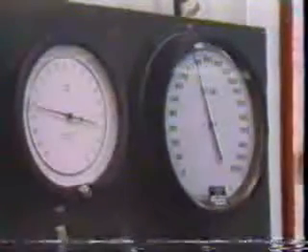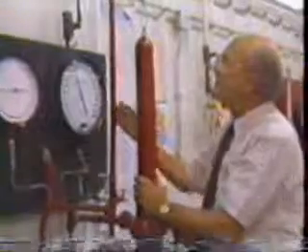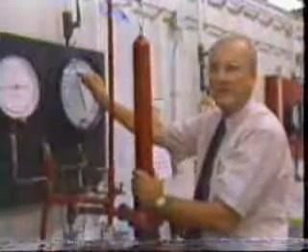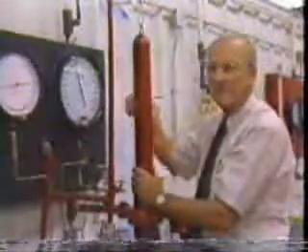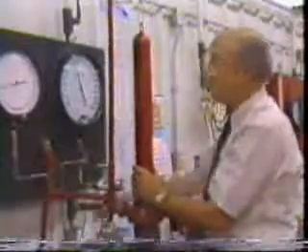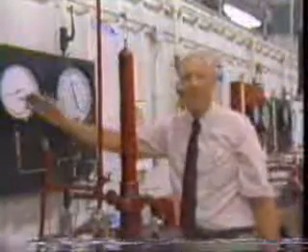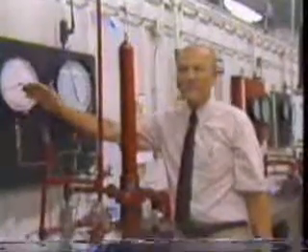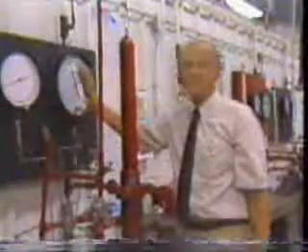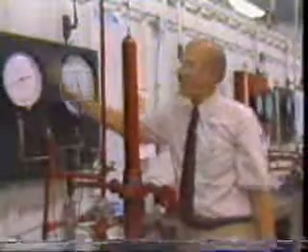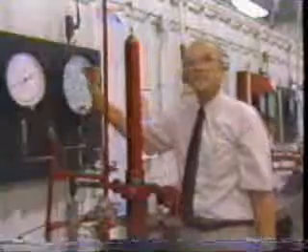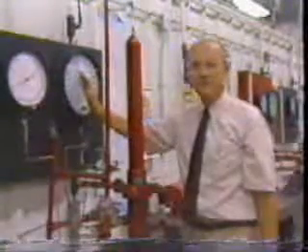When we have lowered the pressure around the valve at a slow rate, we trap the calibration pressure on the casing side as the valve closes. That is the test block closing pressure or the valve closing pressure. This difference in opening pressure on the casing side as a function of the tubing pressure, remember, 300 pounds on the tubing takes over 1,000 pounds on the casing. 700 pounds on the tubing takes less than 900 pounds on the casing.